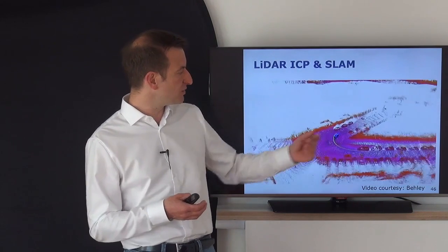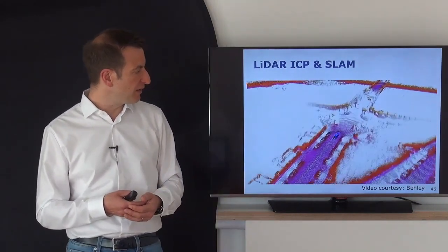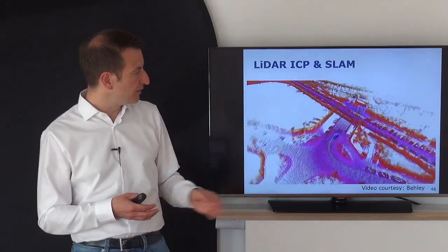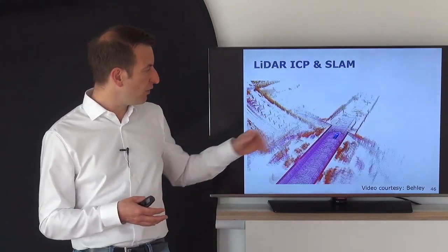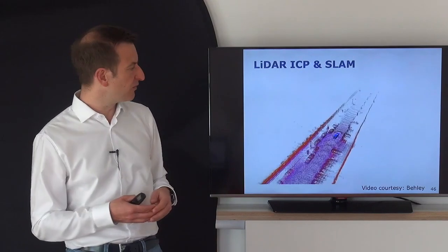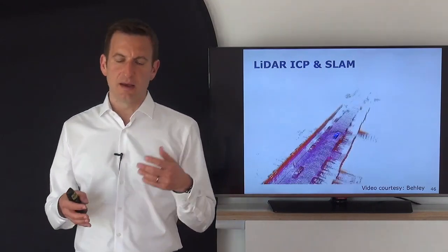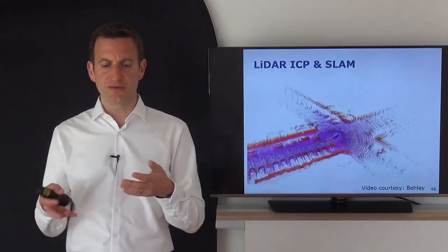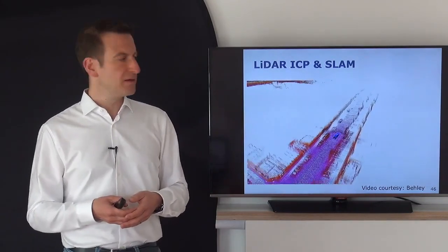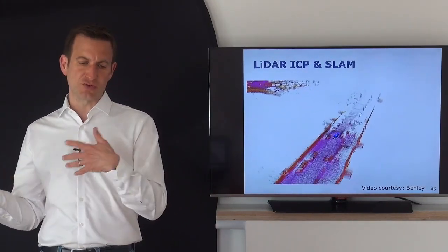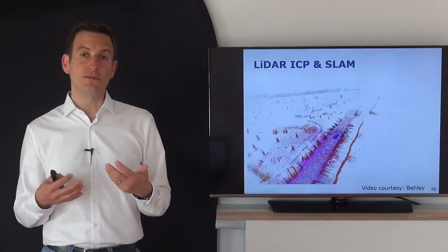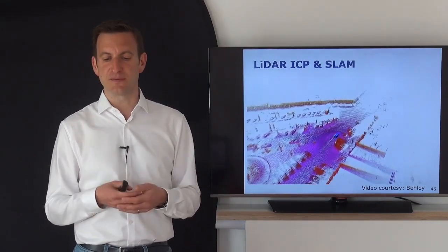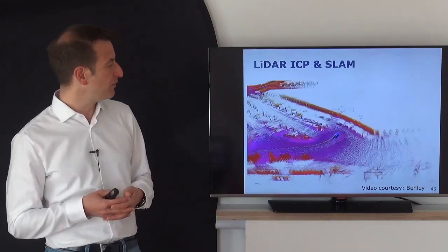So all the pose corrections here are basically done using the ICP algorithm. You can see, the car drives actually over a bridge over that road. It will drive around. This is all basically ICP registrations. It's work developed by Jens Behley, who uses surfels, or surface elements, to match against the current point cloud, and uses a projection technique to project the world into a local view, a range image of the scanner, and then does the alignment using the range scanner.